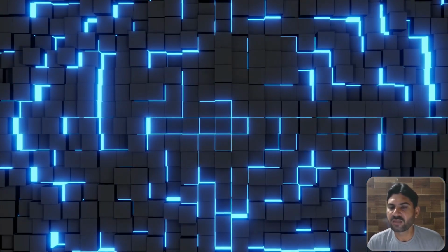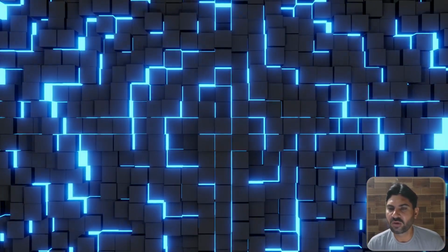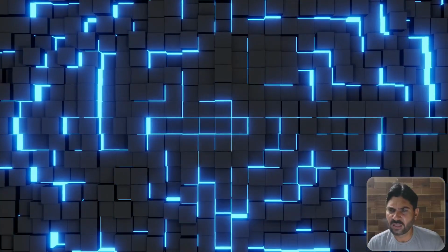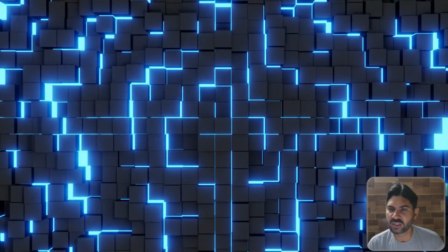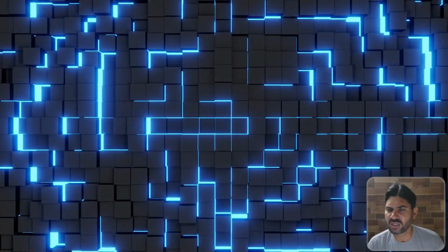All right. In this video, I am going to create this beautiful dynamic 3D background using the Blender geometry node and also a shader node to add some emission material to this structure.